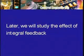And this is what we will take a look at after we have looked at another feedback scheme which I had mentioned a long time ago. What we have looked at right now is only proportional feedback. We will look at another feedback scheme, which is called integral feedback. And we will see that with integral feedback, the effect of the load torque changes can be made 0.